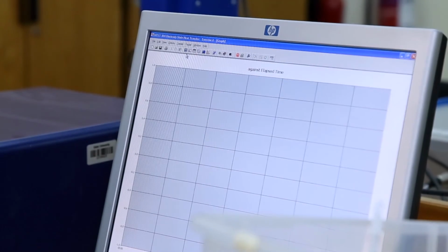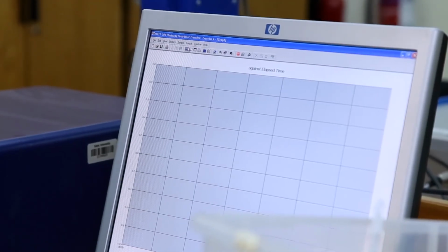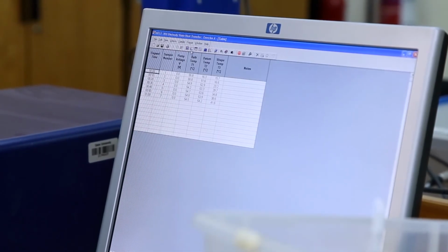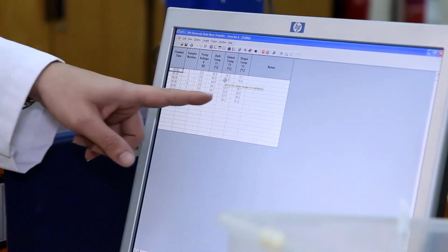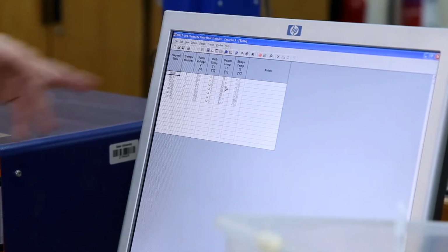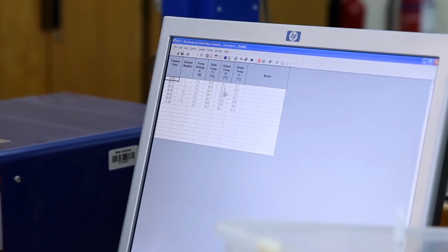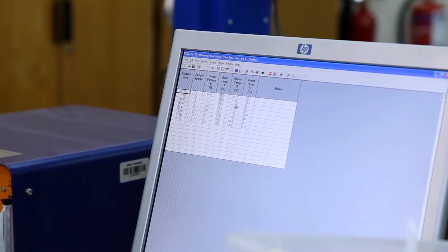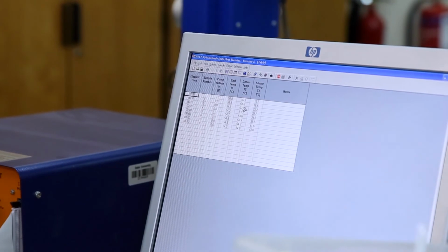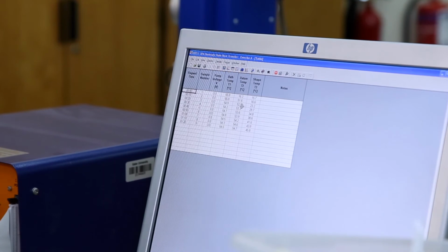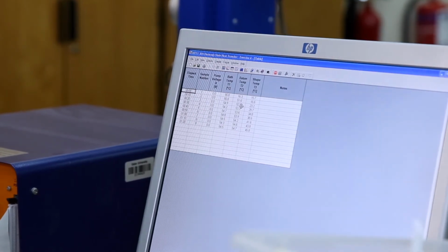So here we should have a curve, but it's not represented yet. Let's go back again to Excel. Now it is 41, so it's almost very close. And as you know, for heat transfer, we start with a huge driving force between the initial temperature and T infinity, and when the temperature becomes very close, the driving force decreases, so it will take a longer time, so the curve will be parabolic.